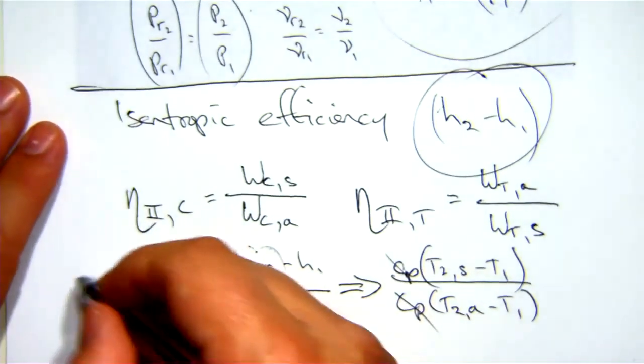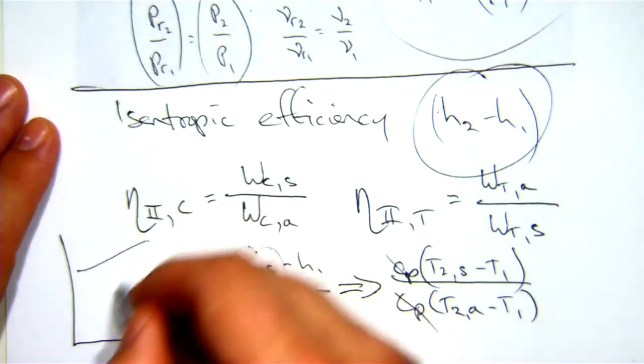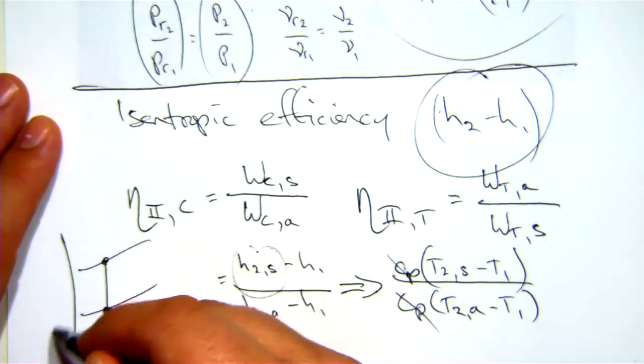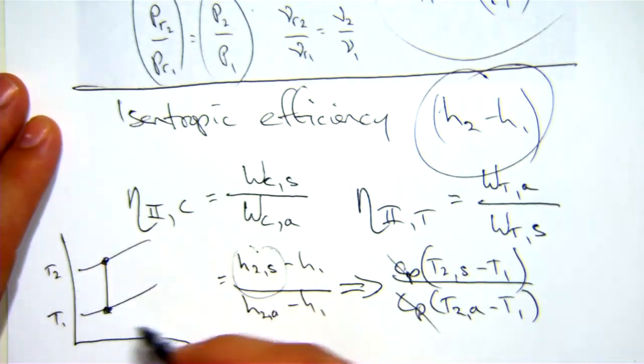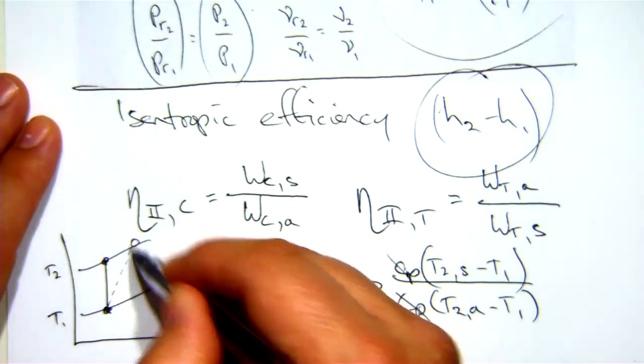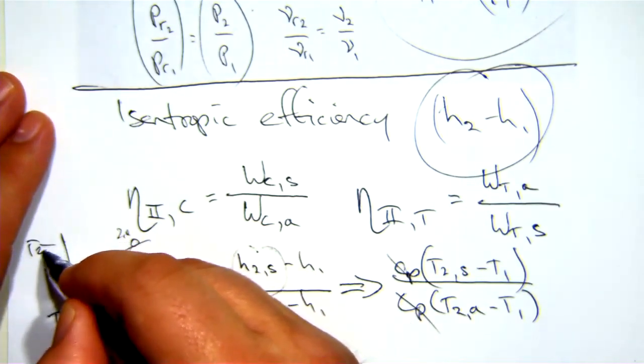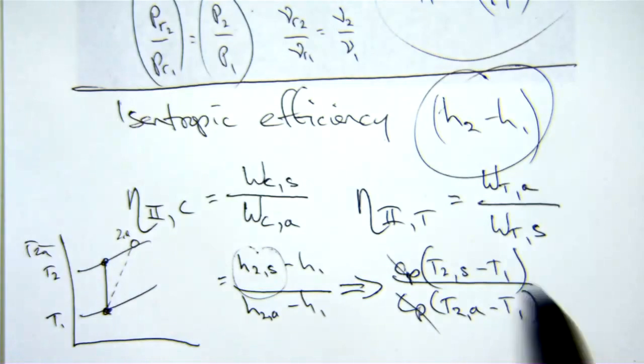And when I go back to my little graph of a compressor, there's my isentropic process from T1 to T2. There's my real process to 2A. I've got T2A. This now gives me a map that says all of my useful tools have been built up for isentropic things, but I know that all things are real and so have losses.